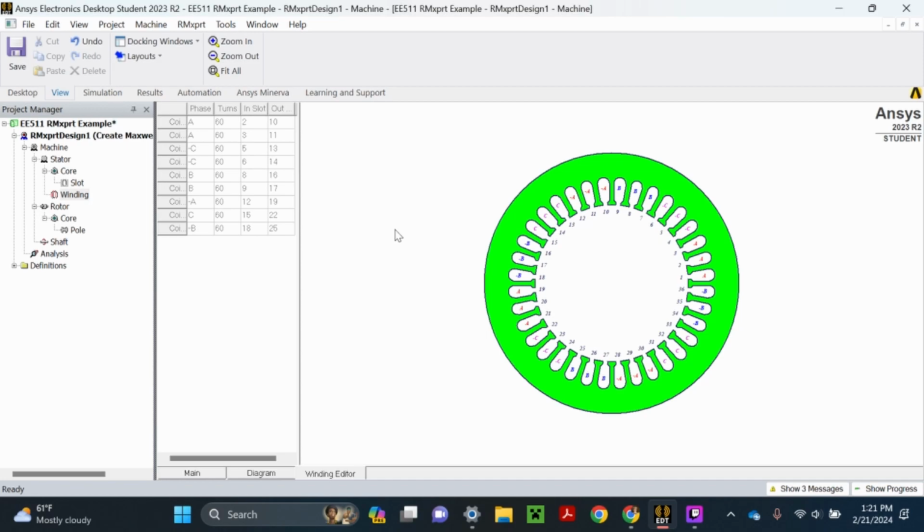Yeah. What he's talking about is something called skin effect, where if you have this really thick round wire at a really high frequency, basically all the current is going to be concentrated in this outer region of the wire, and less current is going to be flowing in the middle of the wire. So then the cross section of your wire is basically decreasing as the frequency increases, which will then increase the resistance. And I'm sure you know that, what is the force that pushes the electrons to the surface? Hall effect. You remember that? It's a Hall effect that pushes them to go at the surface of the wire.